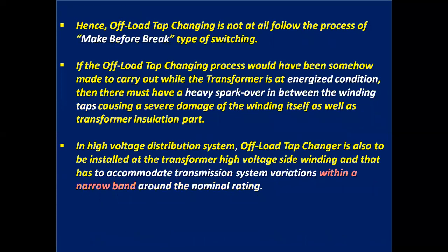Hence, off-load tap changing does not follow the process of make before break type switching. If the tap changing process were somehow carried out while the transformer is energized, then there would be a heavy spark over between the winding taps, causing severe damage to the winding itself as well as the transformer insulation.